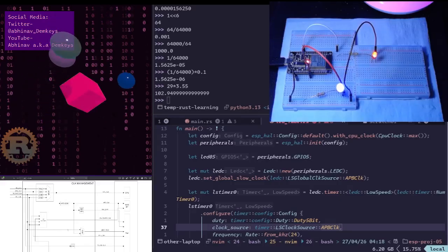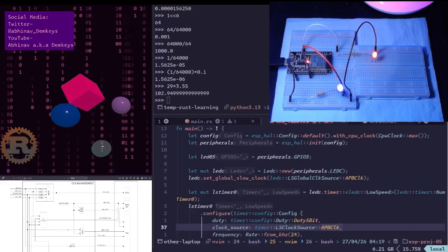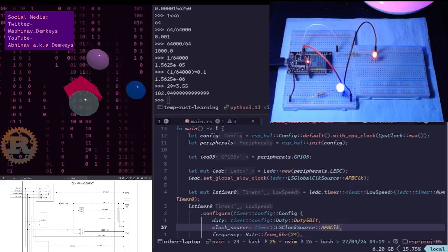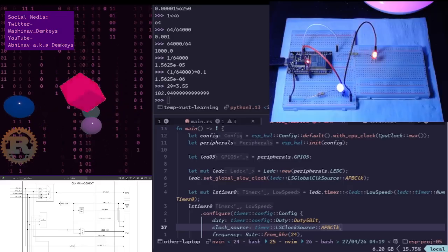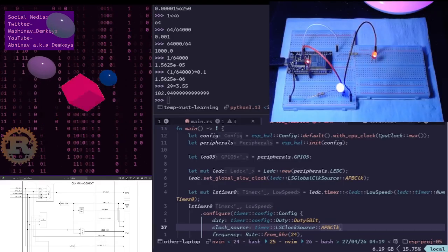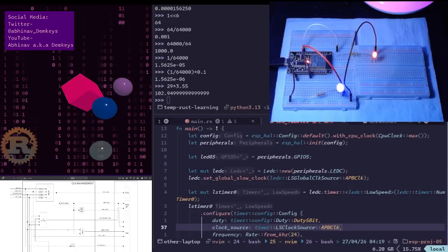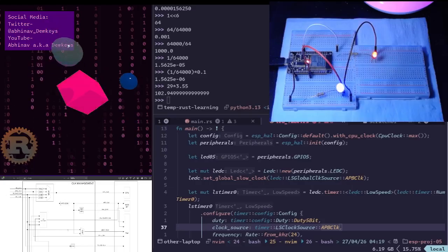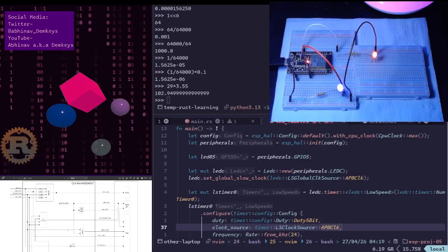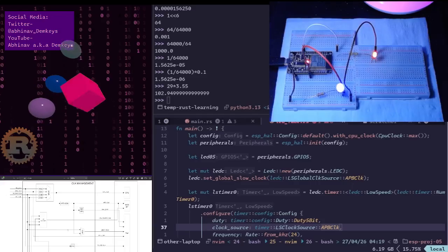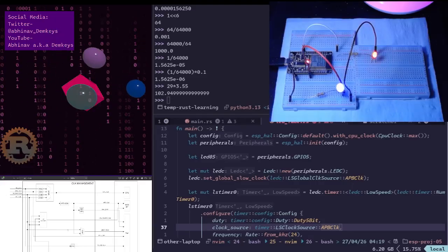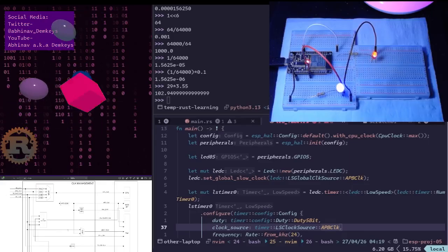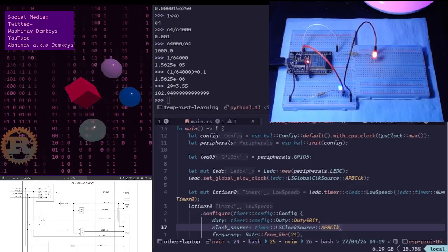Then Gemini said, when using ESP-HAL in a no STD environment, you've hit the sweet spot of embedded development. You have the power to poke every register, but the HAL is designed so you rarely have to. For things like PWM, using LEDC or MCPWM peripherals, you can absolutely build on a quote unquote base level of understanding without getting bogged down in the clock tree every time.